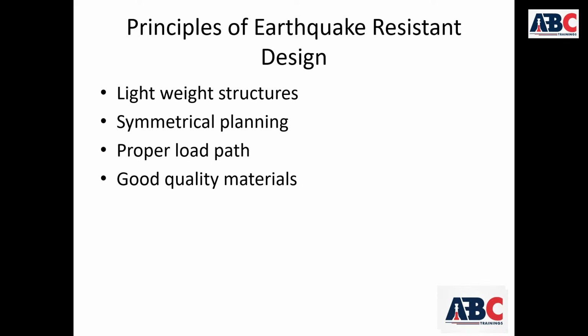Next point is load path. This is one of the most critical principles in structural design. Earthquake force must travel safely from the top of the building down to the ground. This continuous path is called the load path. It includes the loads transferring in sequence: roof to slab, slab to beam, beam to column, column to foundation, and foundation to soil.